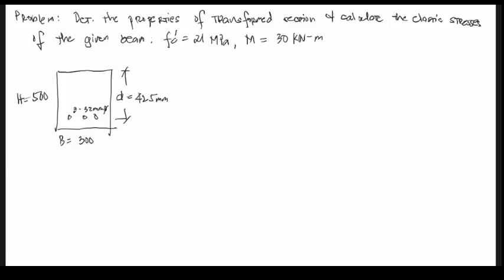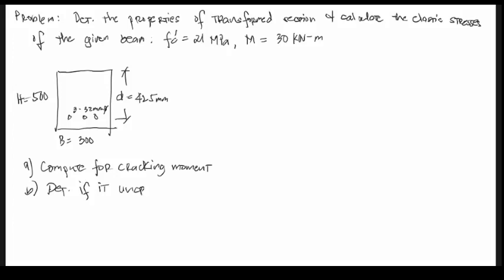So our solution steps, here are our steps. First, compute for cracking moment. Then second, determine if it is uncracked or cracked stage.